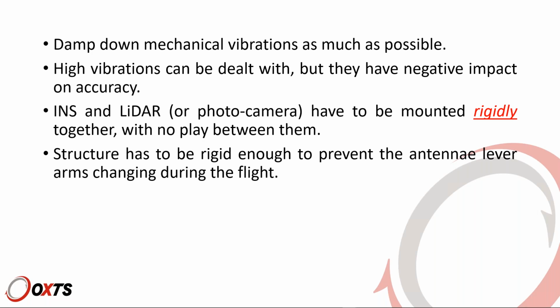No matter what you do in ways of damping down vibrations, you need to make sure that the INS and the LiDAR, or the photo camera, the survey device that you are using, are mounted rigidly with no play between them. So it is fine to damp down the vibrations between the INS and, say, the frame of the drone, the rest of the drone, but you don't have to have any damping mechanism or anything else between the INS and the LiDAR itself.